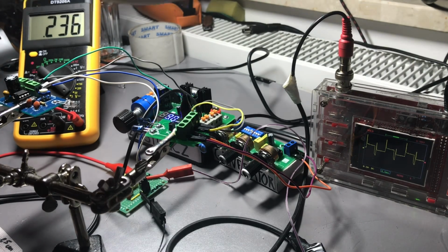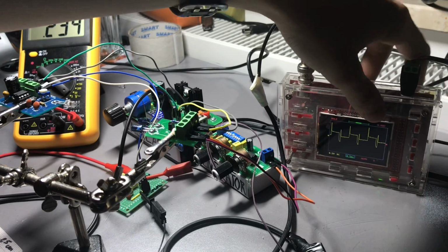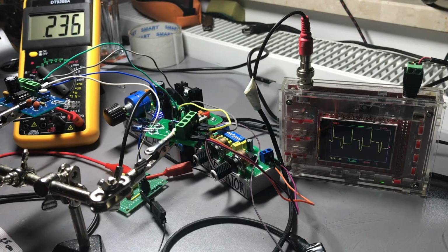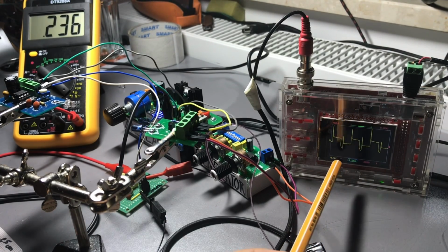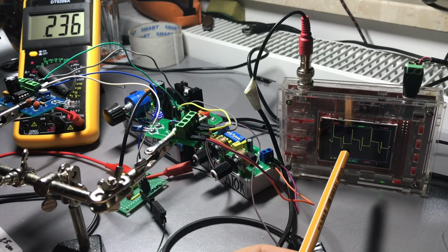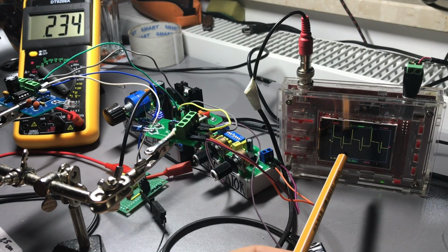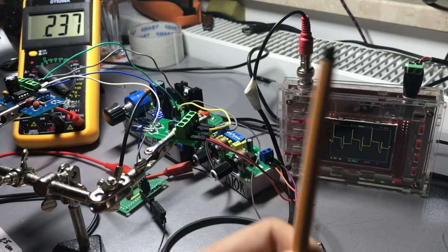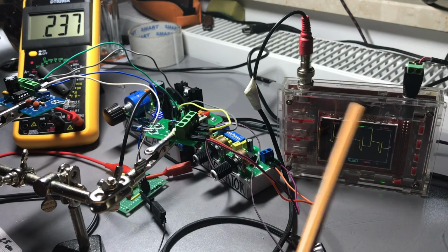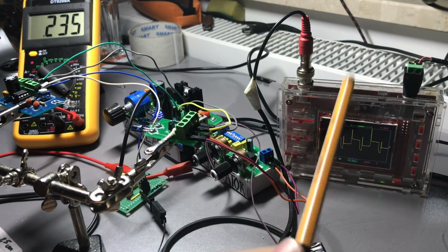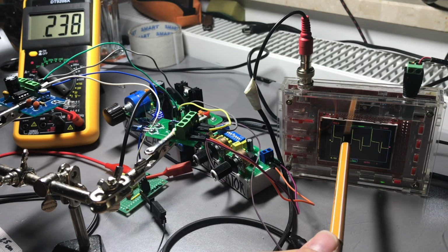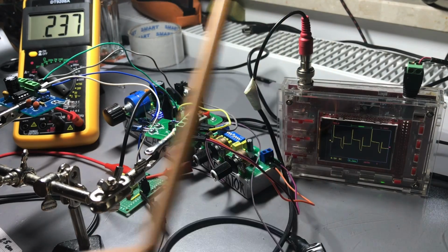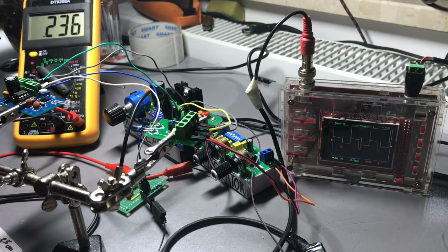And this is another minus. I am feeding a normal square wave into this circuit, but as you can see I get a pretty strange waveform on the output. So this is the second biggest minus of infrared, which is that it doesn't transmit the signal 1-to-1. It just disturbs it a little bit, deforms it, and as you can see, every time it changes we have a high peak of voltage. Of course, if I connect it before the filter, which I can show you, the noise is a bit higher.